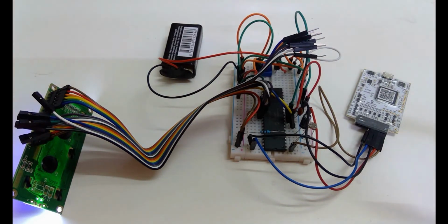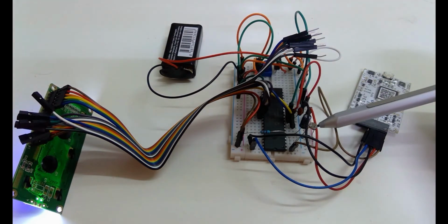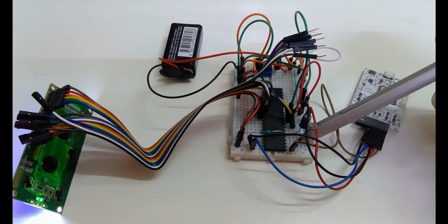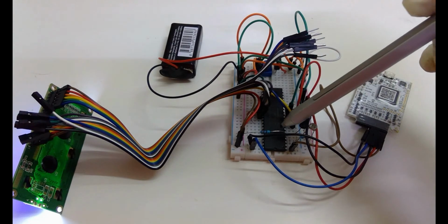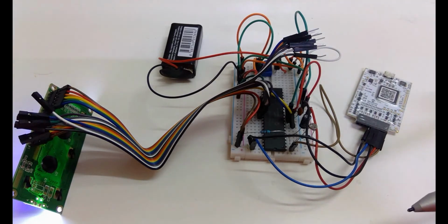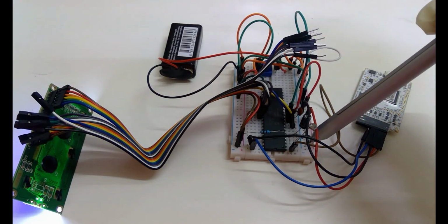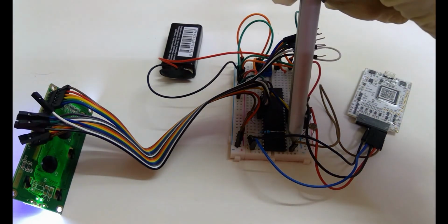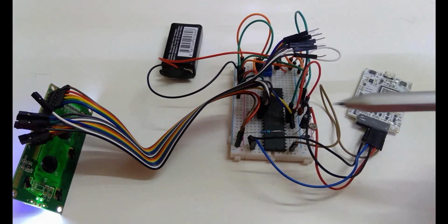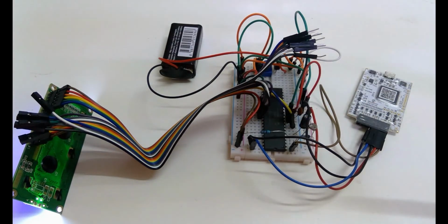So this is the hardware connection on the breadboard. The LDR is connected here. It is connected to the AN1 pin of the microcontroller, and I have connected the 5K resistor, which is connected on the other side, to the ground. So one pin of the LDR is connected to the power, and the other pin is connected to the AN1 input of the microcontroller, and the same pin is connected using the resistor, which is connected to the ground.